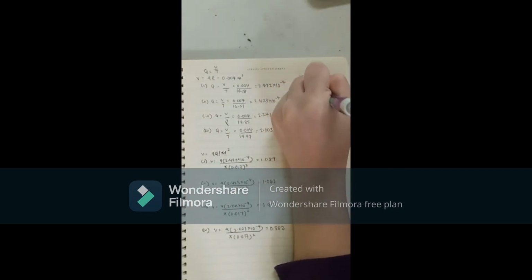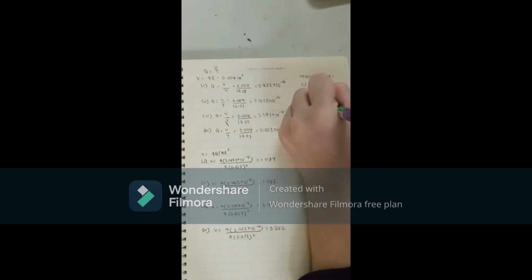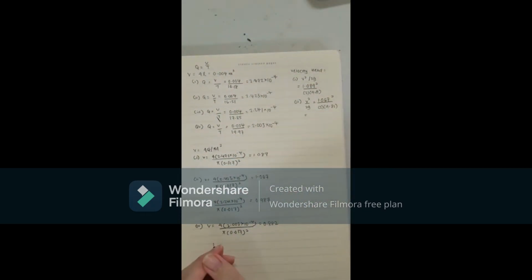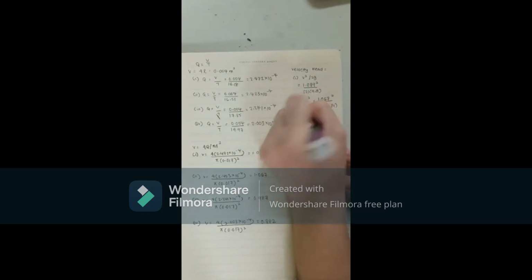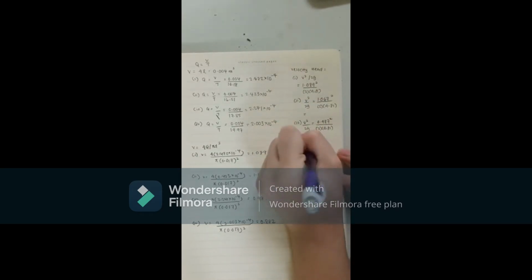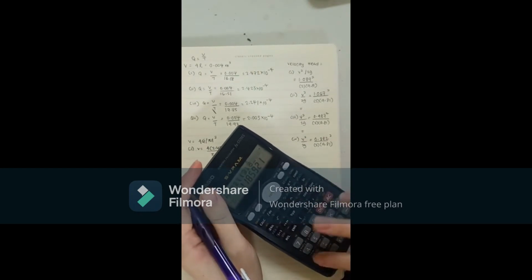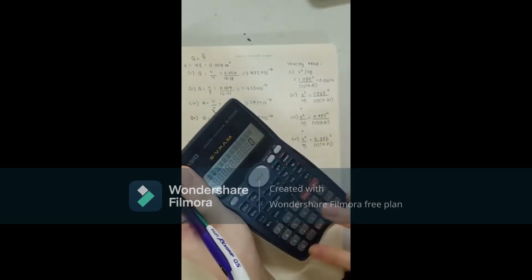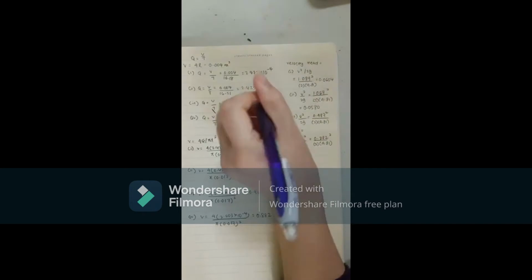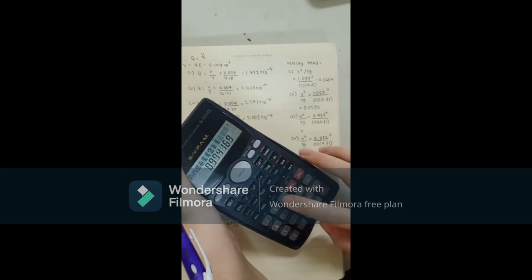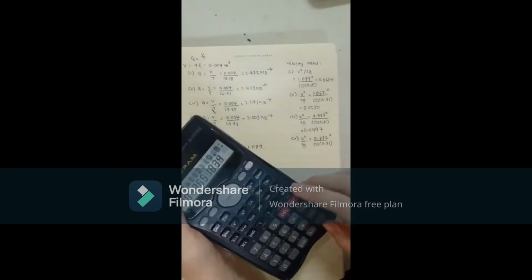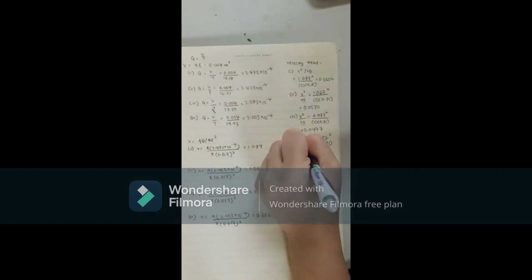And next one, the one that I'm calculating right now, is velocity head, where the formula is v square over 2g. V square is taken from the small v I've calculated just now, and 2g is 2 times gravitational acceleration, which is 9.81.